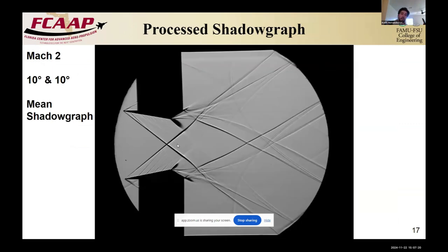But first, I essentially created shock generator models, which we can call 2D stores, where instead of a conical shock coming off of the store, it's just a planar shock. And here, it's very fundamental, and I'm just studying the interaction between these shocks, which we can later extrapolate to the 3D flow of the conical stores.